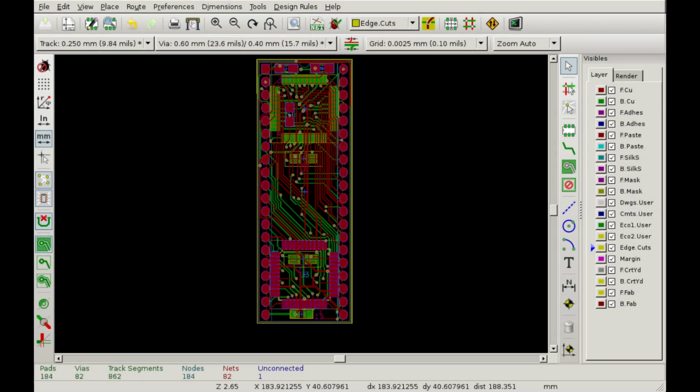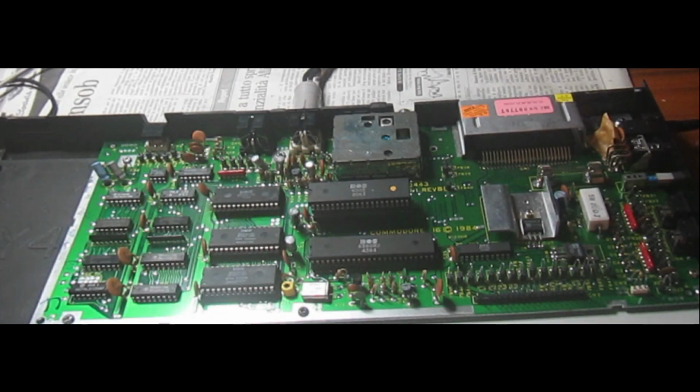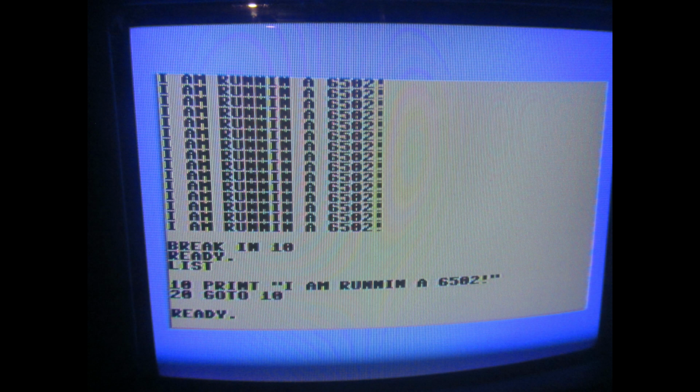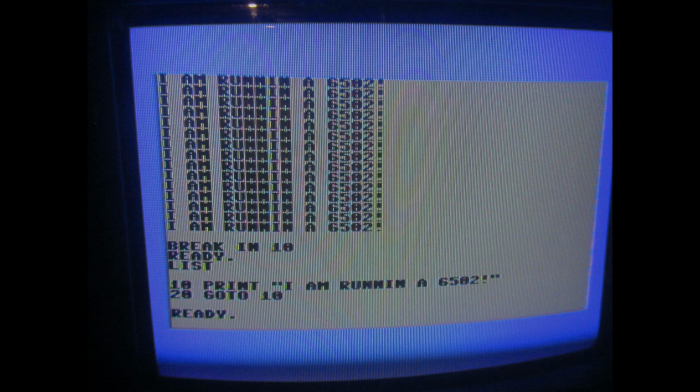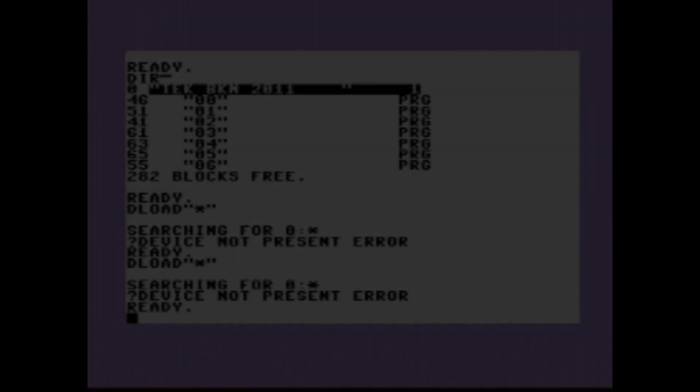This is the second part video covering my attempt to replace a MOS 7501 CPU for the Commodore C16 with a 6502 CPU plus some logic add-on made with two 32 cells CPLDs. In part 1 I realized the first prototype, and that made the machine boot apparently fine and also run some simple test programs. However, it was soon evident that the C16 had issues, and in a very random manner too.